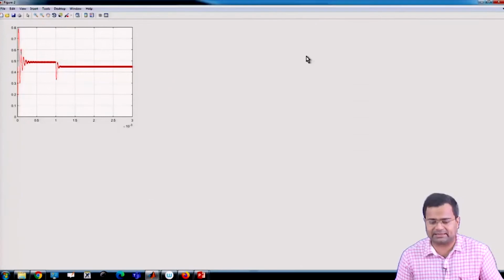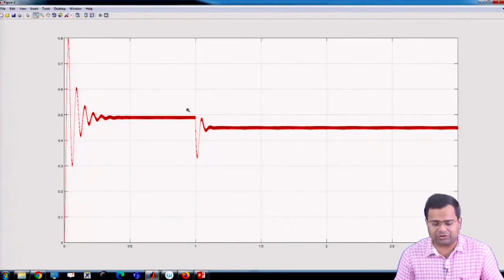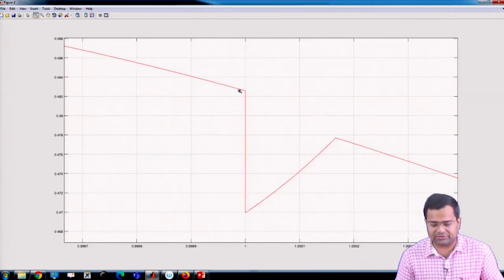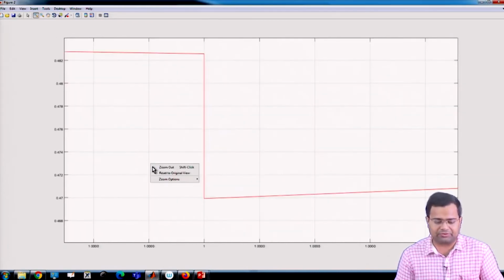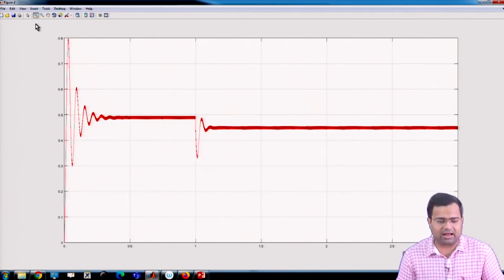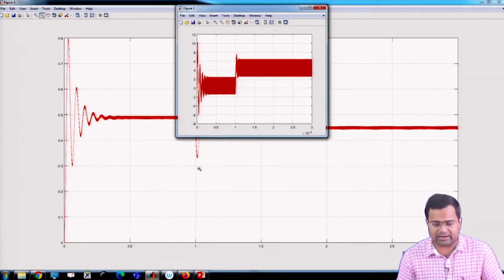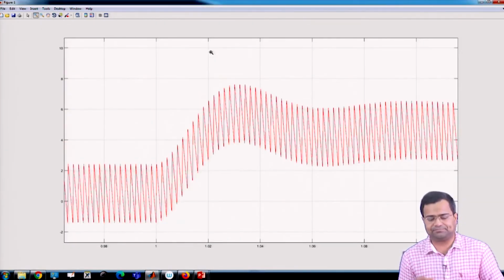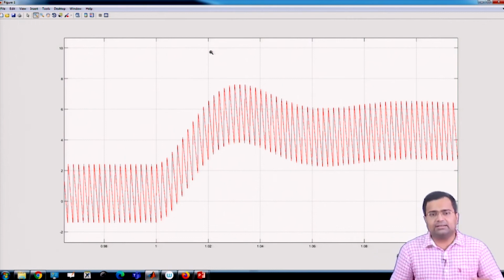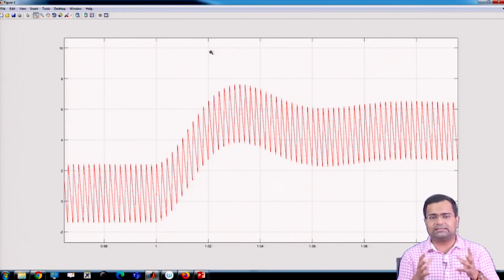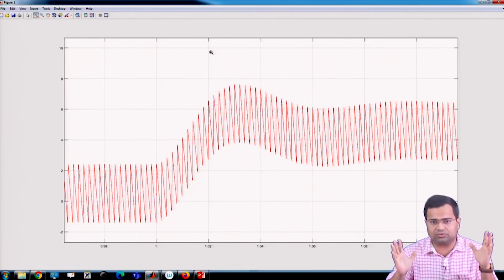Now it shows the complete simulation, and it also joined that discontinuous line where we got some discontinuity. This was our point of discontinuity, because we have clubbed together both the simulations and they can run. So, we have created a case study where the inductor current also we have merged them together. That means we learn how to simulate a transient case study. This is in open loop, but we can do it in closed loop, there is no problem.